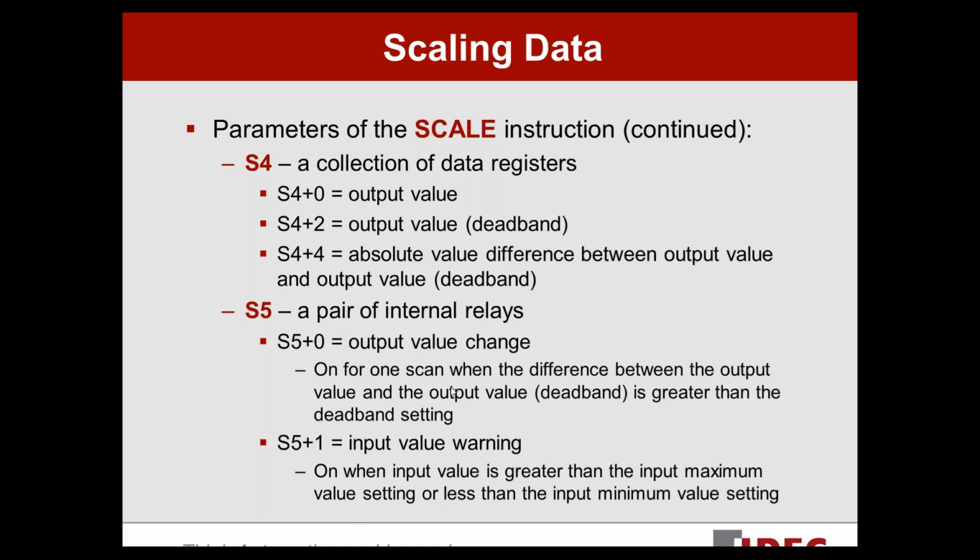know what the scan is, the scan of the PLC is a 4-step process, and this is common among pretty much all PLCs on the market. Basically, what the scan entails is a process that reads all of your inputs, executes your logic, updates your outputs, and then does housekeeping and communications at the end. Okay, so it's a 4-step process. How fast that happens is called the scan time. And you'll see scan times of PLCs, depending upon your program, how big it is, what's turning on and off on each scan. You'll see scan times in the neighborhood of 5 milliseconds, 10 milliseconds, 20 milliseconds, in that kind of a range.